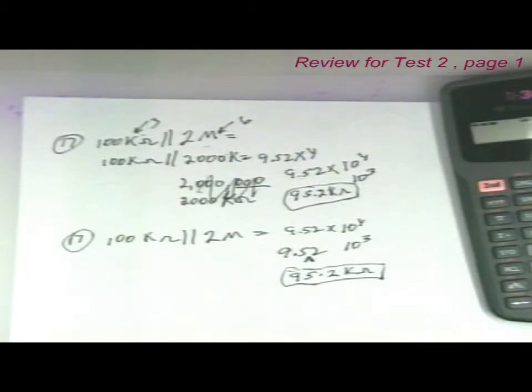In a parallel circuit, the largest amount of power is dissipated by the smallest resistor. We discussed that earlier. We discussed it in lab. Okay. A short is like a wire or a ring or whatever goes across the circuit. A short in one branch of a parallel circuit results in an increase in current flow.